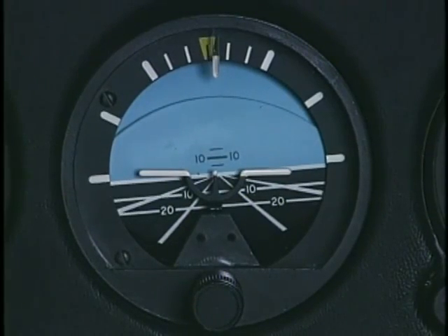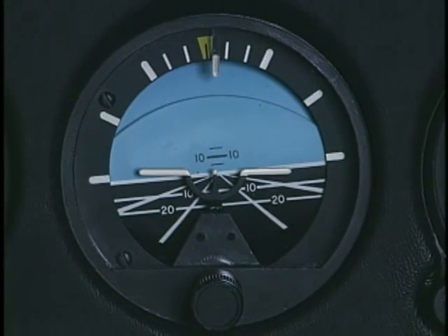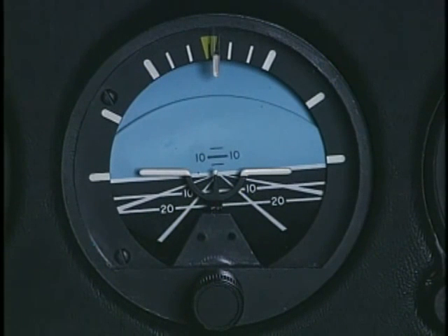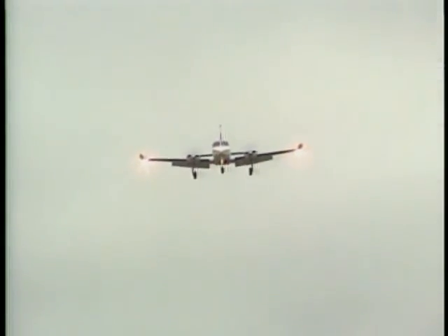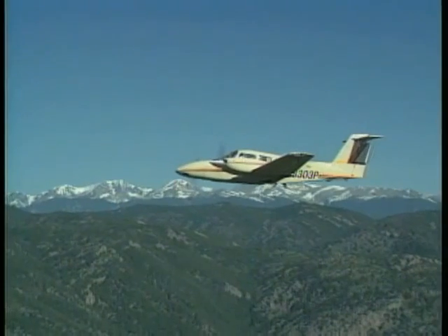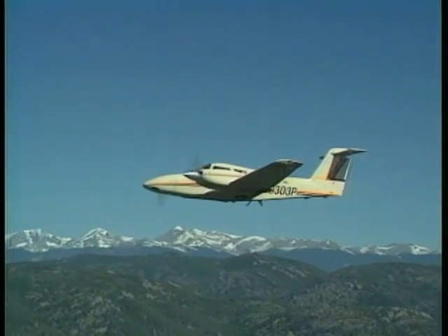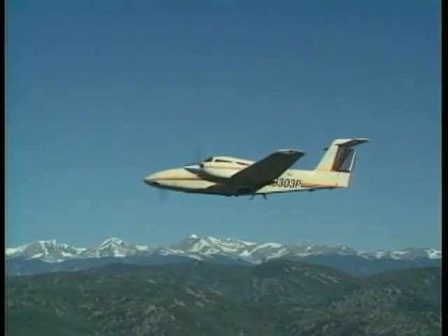Less than a 5-degree bank may provide the best controllability and performance. You may recommend that the pilot initially establish a 5-degree bank and then reduce the bank slightly to determine if a smaller bank angle will have more positive results in performance. In addition to factors listed in the certification regulation, conditions to include in your discussion are the effects of density altitude, airspeed, extension of flaps, and benefits of feathering the propeller. One of the important goals of multi-engine training is for the pilot to obtain a complete knowledge of how specific factors affect controllability and performance in engine-out situations.